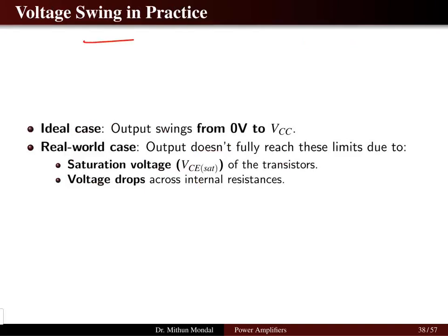The voltage swing, which is from 0 volt to VCC, is for the ideal case, but in the real world it may not reach this limit because of saturation of the transistors and voltage drop across the internal resistances.